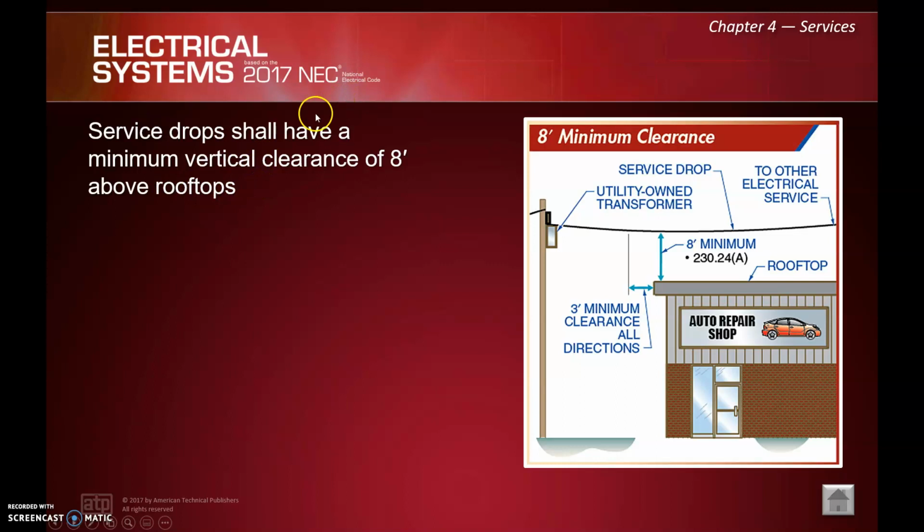Service drops shall have a minimum vertical clearance of 8 foot above roofs. That's a flat or fairly flat roof, that is. We need to be at least 8 foot.